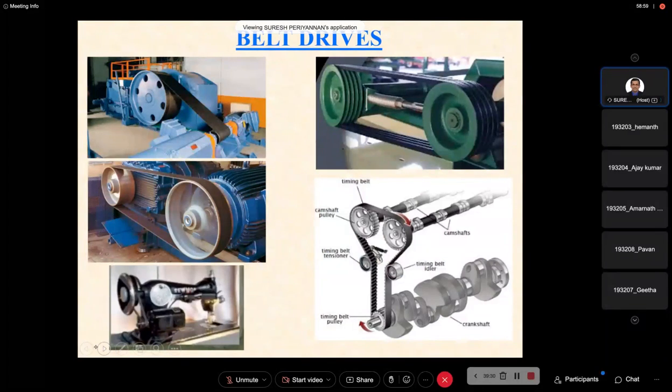See here, then you can easily understand. This is a wedge, trapezoidal cross section. Here the coefficient of friction is high due to more contact region, due to wedge action, and the arc of contact is also small. Hence the coefficient of friction is high, the friction resistance is high, and then we are able to transmit more power.